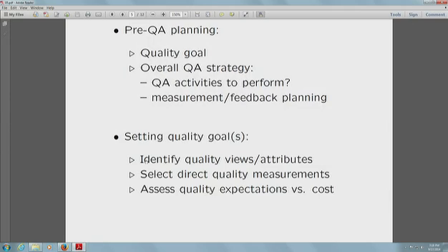No easy repair. Now imagine your other one goes down every week on average, but it takes just a couple of seconds to repair and get it running again. If you give this to someone who is supposed to run something continuously, then this one with the lower reliability is actually better, because it has better repairability, and so in terms of overall availability, when it's available at any given time, it's better. Okay, so you have to look at what is most important to your customers, and then set a goal in terms of that thing.